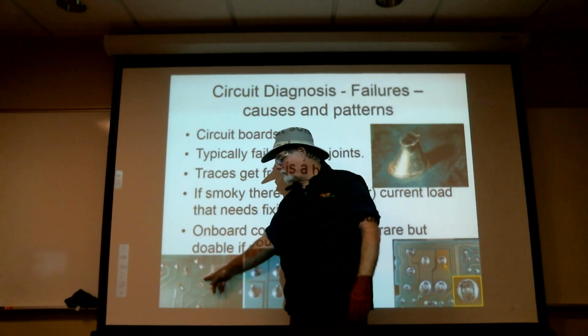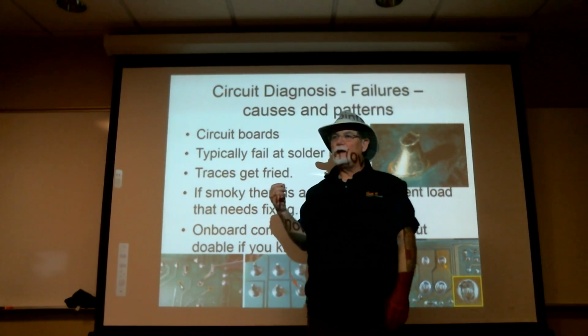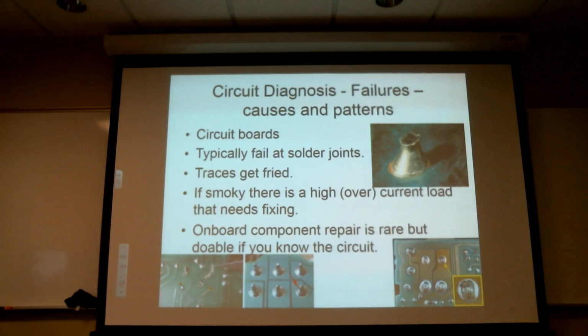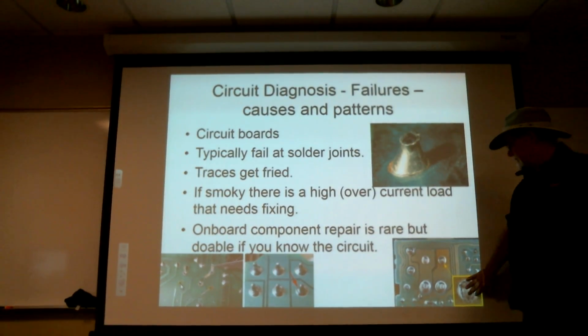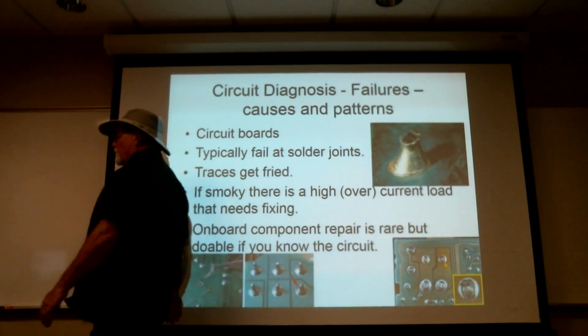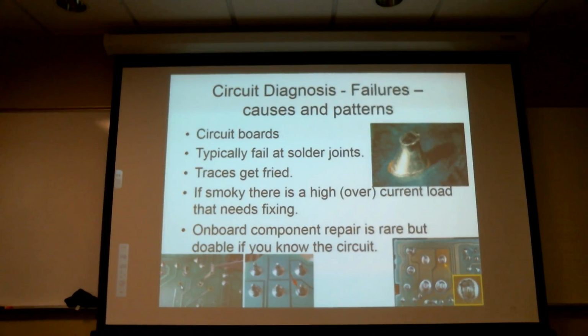it'll cause the glue to debond, and that trace will come up. And it's a pretty thin trace. It tears real easily once it unbonds. So given a number of those are torn and damaged like that, my general guess is the soldering technique was too hot for there. But this is really, really, really probably the most common circuit board failure out there.